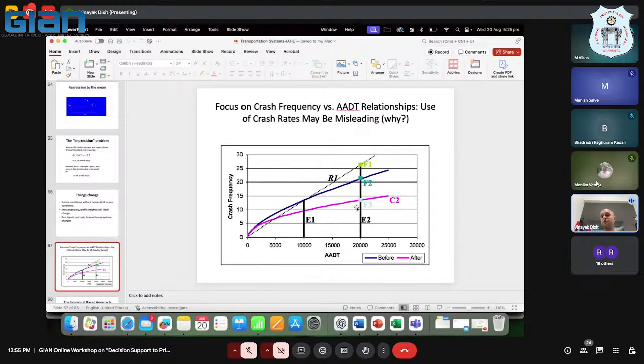If we do F1 to F3, we are overestimating. If we look at F3 only, then we are underestimating, because we'll say that there's no impact. So it is basically F2. We develop these safety performance functions, and this is where the crash modification factor comes in. The difference on this curve is because of the intervention, the crash modification factor of the intervention.